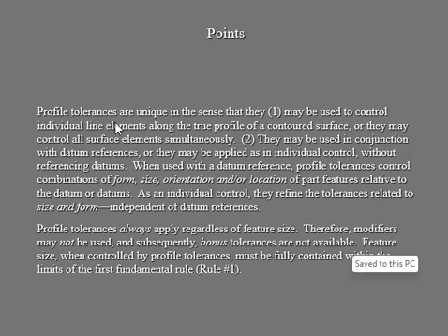We're just trying to tell what the profile tolerance is. Of course, when you're profiling, we're looking at the surface, your contour surface. So that's what we'll be dealing with. And then, of course, it has to be used with your datum reference, because without the datum references, you can't do any kind of measurement verification. That's how we measure. You need a datum reference to be able to measure and check that all these size dimensions are within the acceptable tolerance zone.